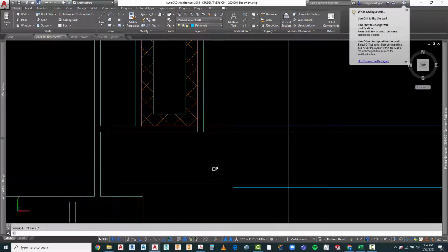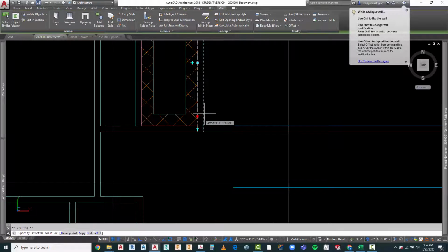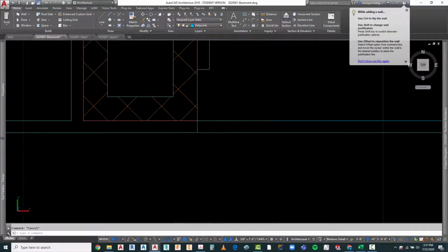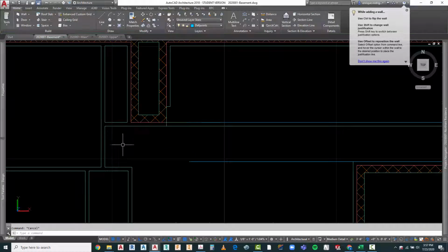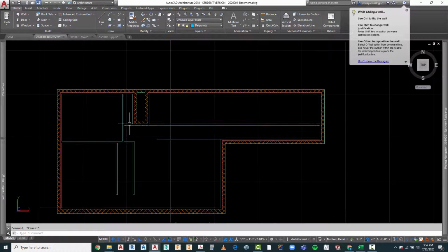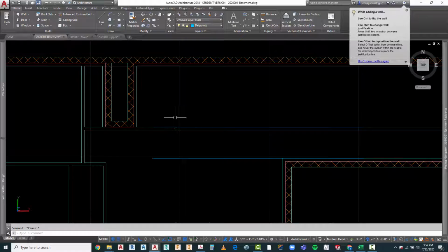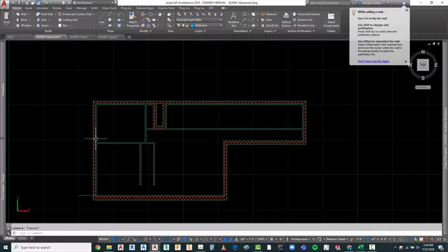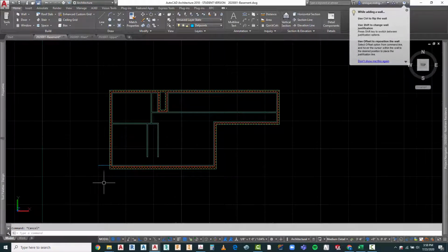Okay. So what I want to do is make sure that this is a clean solution in there. I've got 2 walls in there. I don't need them anymore, so I'm going to clear this out. And I'm going to go ahead and extend that out to there and extend this down to here. So now to me that's a much cleaner solution all the way along there. I'm going to find my line, delete it there, and delete it there. Now I could theoretically push this up, but that's a huge problem in terms of the bearing location for that wall. So this looks good to me the way that it's shown.